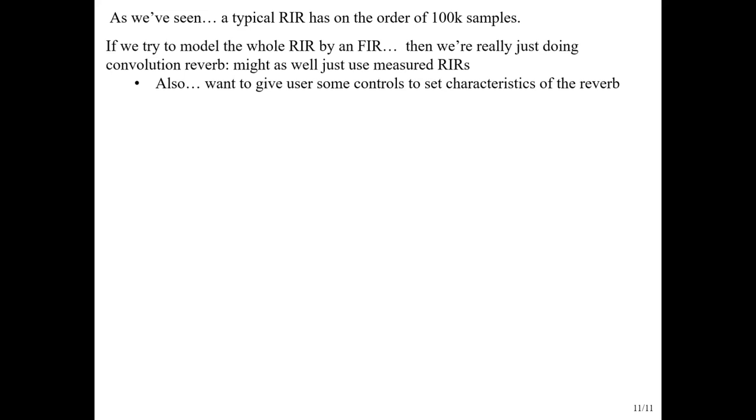So if we were to take that impulse response and try to model the whole thing with an FIR structure, that's just doing convolution reverb. We might as well just take the measured room impulse response and put it into Gardner's algorithm and be done with it. But that's not what we're trying to do here.